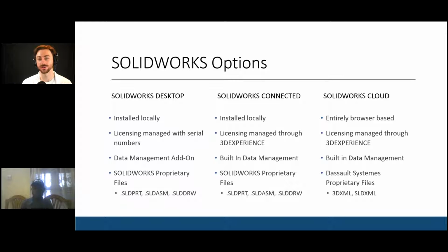It's a set of SOLIDWORKS tools, but they're built to be in that browser and they're not a file-based system, so you're dealing with a Dassault Systèmes proprietary data type that is exported as a 3D XML or SLD XML, and you can always, of course, export to STEP and IGES as well.